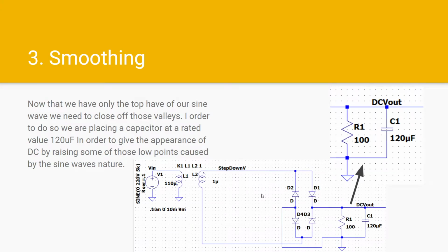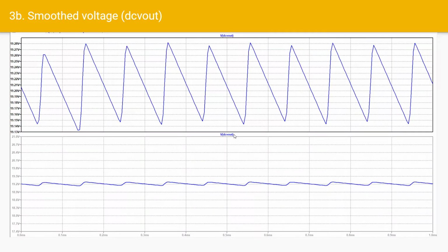I pretty much was putting the 110 microhenries on the right side and the 1 microhenry on the left, because I thought I was doing a 1:11 ratio, but instead I needed, for every 11 turns here, we produce 1 turn over here. The issue was causing us to try to do a step up instead of stepping down, so that was causing further issues down over here, which was just creating anomalies in the simulation that really didn't mean anything at all.